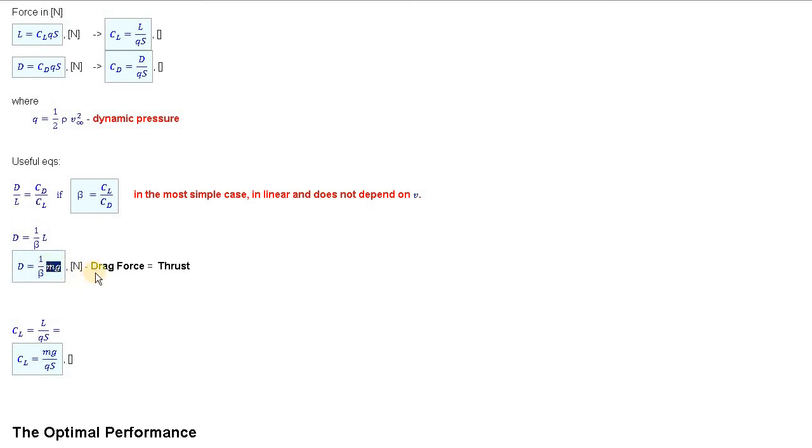So you need the engine or engines with thrust equivalent to mg. Whereas for the plane, you have to divide this mg by the beta, which, in the case of the long wings, is almost 30. So you need around 3% of the power if you compare it with the power of the drone. So that's why planes are cool.